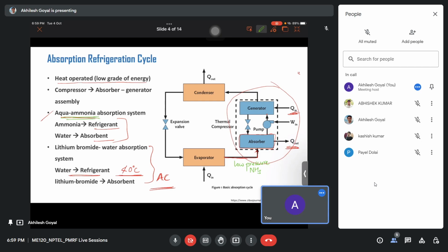Okay, so this heat is given out. Now the amount of this heat release, this latent heat of condensation, again depends on how much ammonia is being absorbed in the water, right? Low absorption means low heat release, high absorption means high heat release.